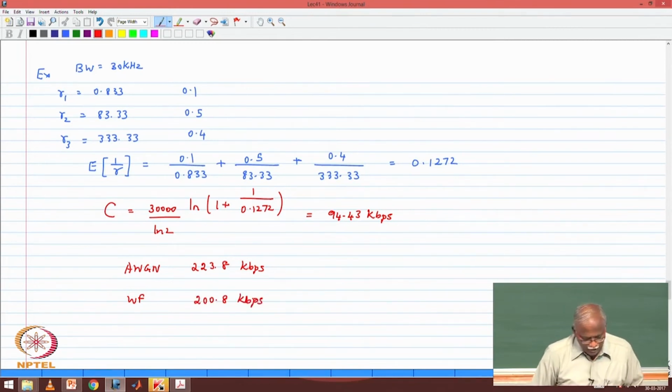Okay. Now, never give up if it doesn't work the first time. Now you say, well, what did we try to do? We tried to invert the channel under all conditions. Say, no, I think I know from channel capacity that it's not worth spending your resources on very bad channel conditions. So we now say that, okay, we're going to do something called a modified channel inversion, or what is called a truncated channel inversion.